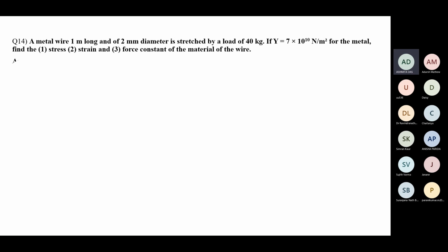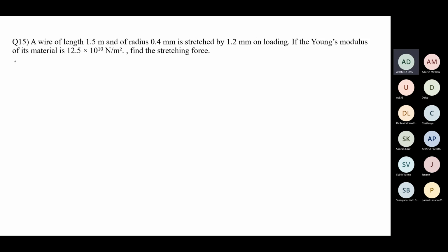So I'm moving to the next, last question. A metal wire of length 1.5 meter and radius 0.4 millimeter is stretched by 1.2 millimeter on loading. If the Young modulus of its material is 12.5 into 10 to the power 10 Newton per meter square, find the stretching force.